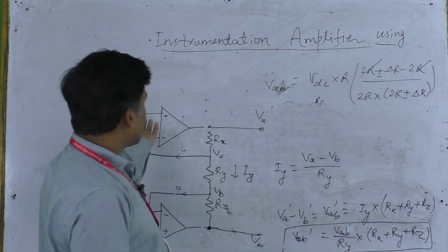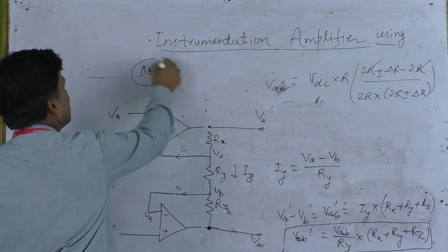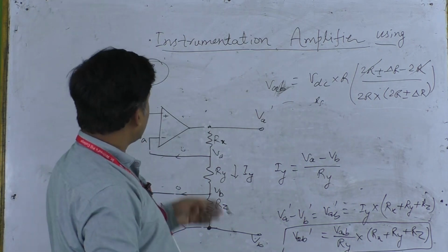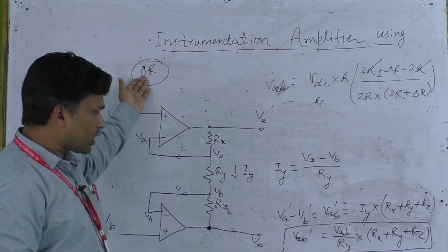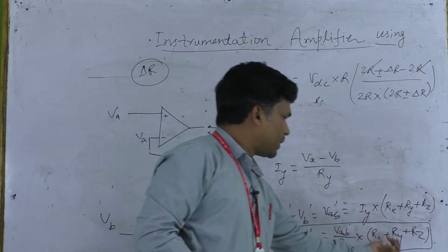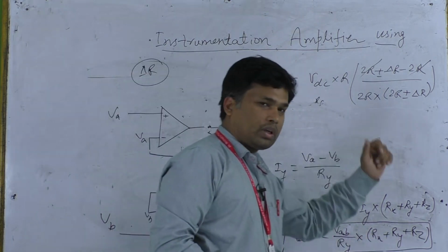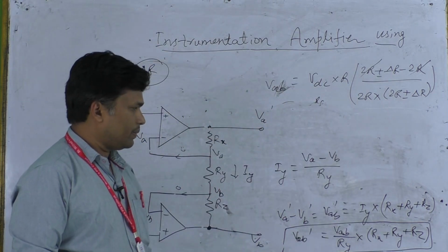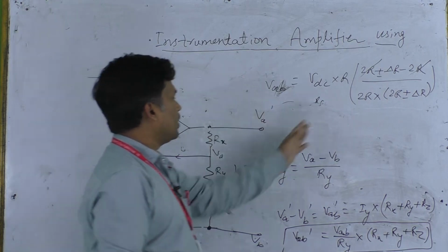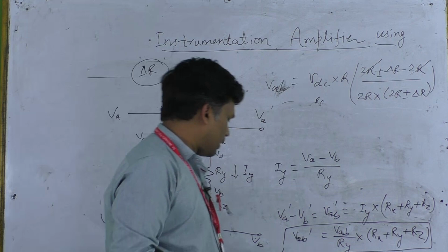That means whatever you are sensing, your resistance will change the value through delta R. If that particular voltage difference created due to this change delta R is not sufficient, in such a case this particular gain will amplify those changes and you will have a large output at the output of the instrumentation amplifier. Further, you can increase the gain through the second stage of the instrumentation amplifier.